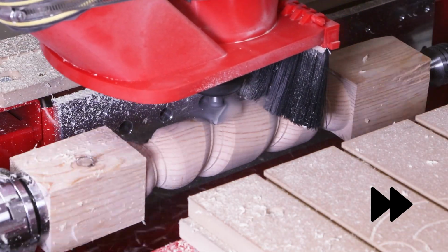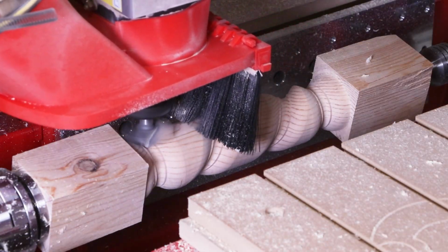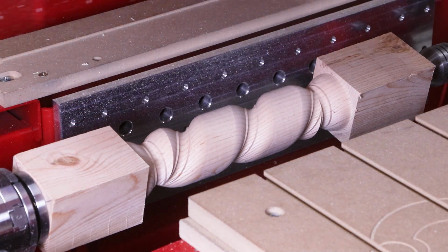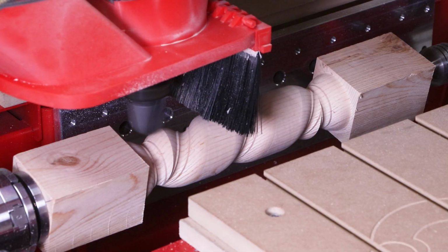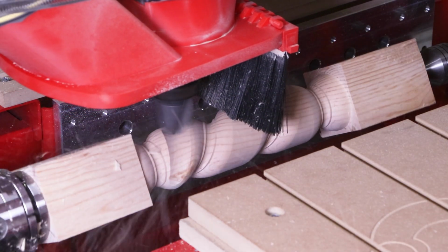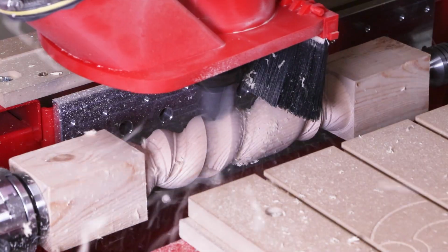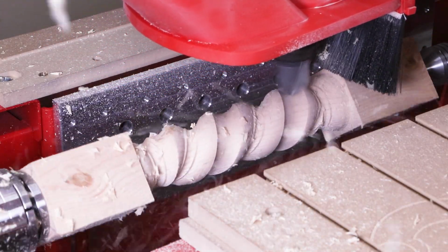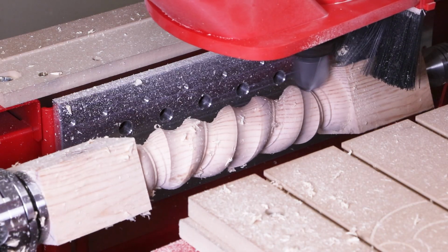At the end of this first spiraling process, you can see that it lifts up and then rotates 180 degrees, repositioning it for the next cutter. The core box cutter repeats the exact same process, but because it doesn't have to cut as deep as the classic spiral cutter, this is going to perform in 2 passes instead of 4.